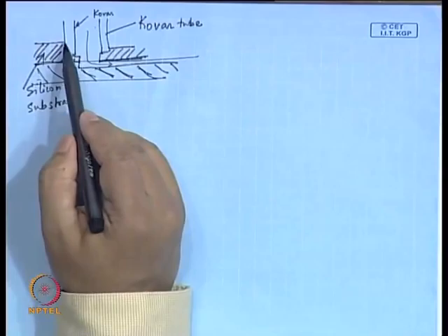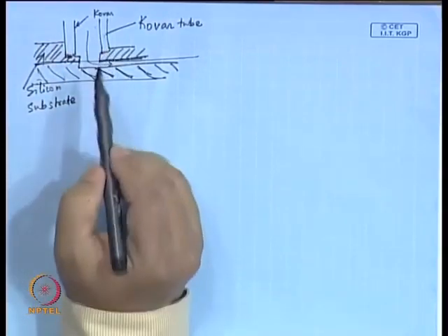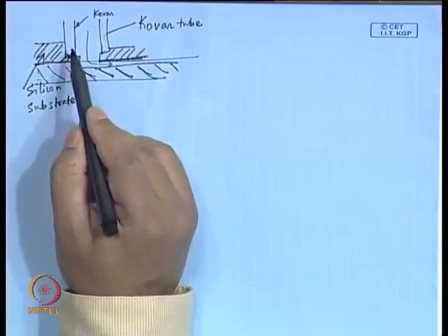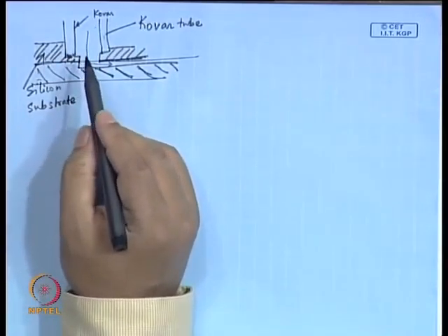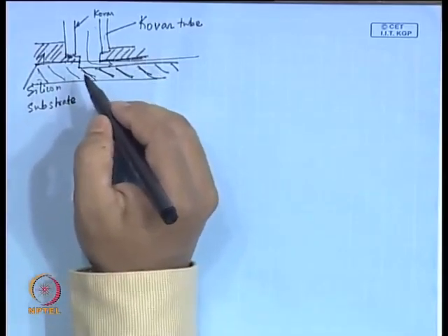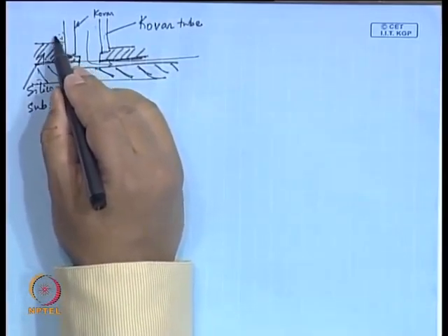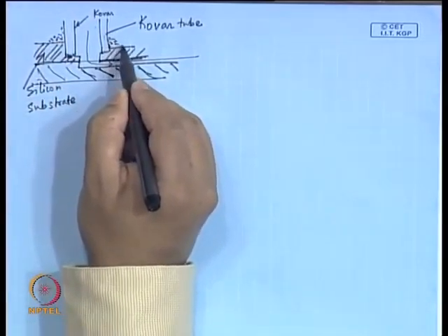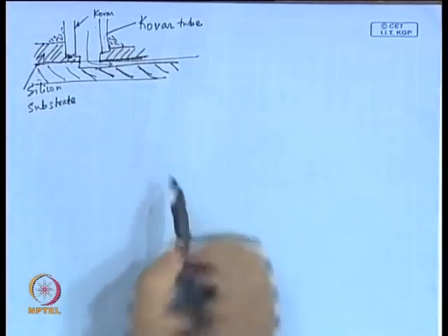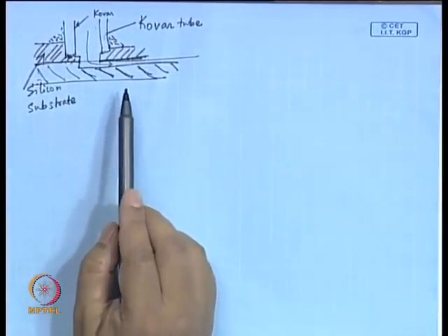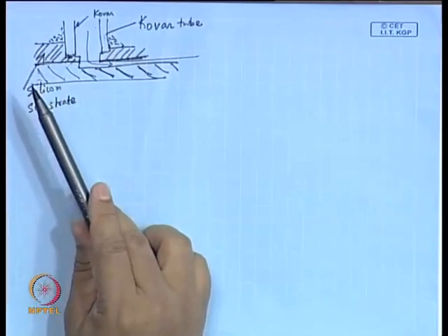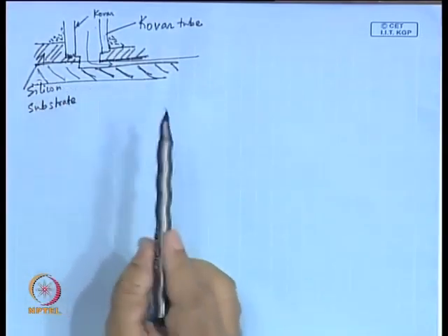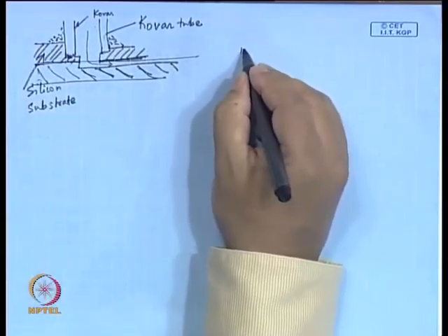Now, this portion is roughened etcetera, and they go in there. Now, you have to do the bonding, and since this is a metal, the common method of doing the bonding is you put small glass beads around this corner, and then you place a carbon fixture around the joint and anneal the assembly at 1020 degree centigrade.